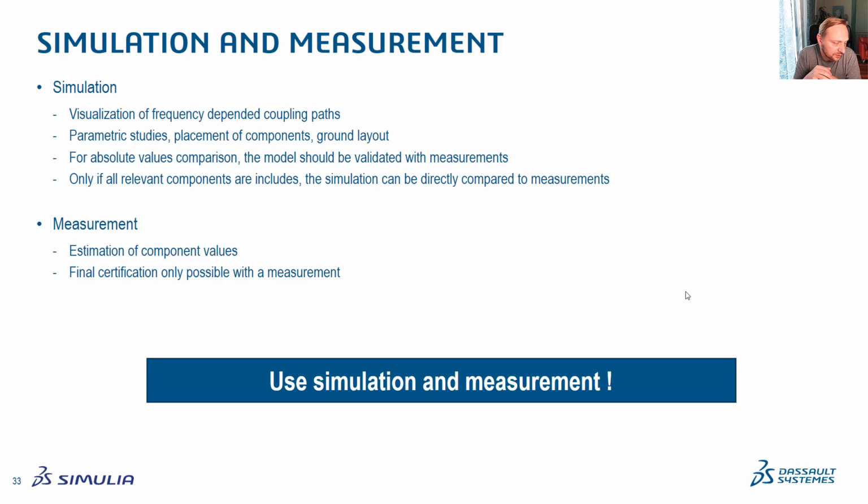The advantage of simulation is being able to visualize things and run parameter studies like I did. Moving the capacitor, making these capacitors more symmetric, takes me something like 20 minutes. In measurement, you would need to order a whole new PCB layout, which would be much more time consuming. On the other hand, with measurement you can get a good idea of your component values. If your manufacturer doesn't provide component values, you can measure the component and use the measured values directly in the simulation. You can load the measurement of a capacitor, put it on the schematic and use it.